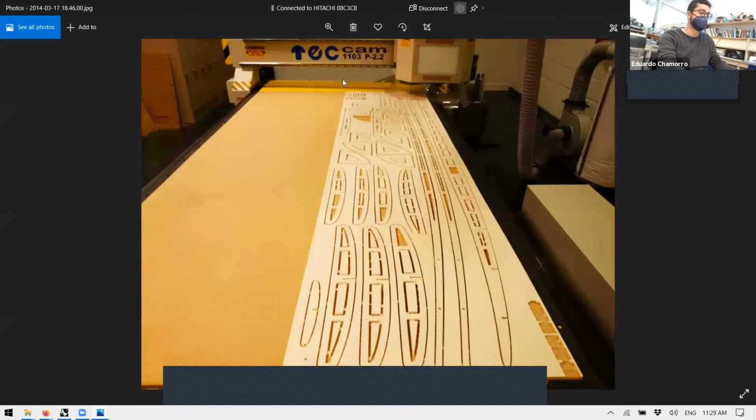This machine, you can see the bridge is small. Also, this machine is not especially meant to do a lot of three-dimensional movements, because this is a machine for production. It has a vacuum bed, which means you put your board, you attach it, and in 2 seconds you have fixed your material. Second, the bridge is small. That means the machine is even sturdier because there is less cantilever on the machine. And they have this to collect the dust and keep every area clean.